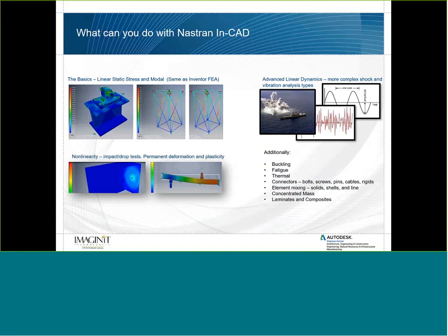We have the basics, our linear statics. We have modal analysis, so what are the natural frequencies of our components in our assemblies? But then nonlinearity we have with Nastran CAD as well, so we can do some impact and drop tests, looking at time steps and time-dependent response, as well as looking at deformation.